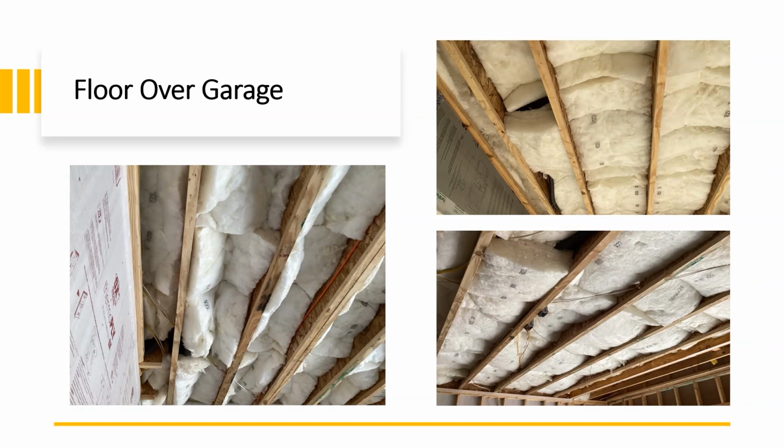It looks nice, it looks pretty, but the one on the bottom, I took that photo, I pushed the bat out of the way, and there's a massive gap to where it goes to the conditioned floor. I could tell it wasn't double lined. It's only 6 inches deep. Those TJIs are 10. That's a massive gap. They're going to have to fix that.